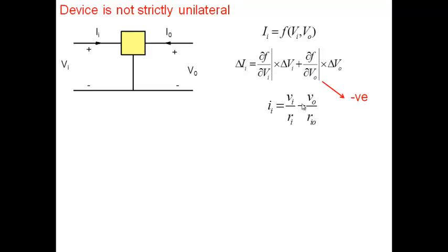So strictly speaking, the input current that you see here has these two terms. I can write this particular input expression as Vi by Ri. I add a term and subtract a term, Vi by Ri0. So we add this term Vi by Ri0 and we subtract it also. Because what we want is to modify our original small signal model with the idea that there